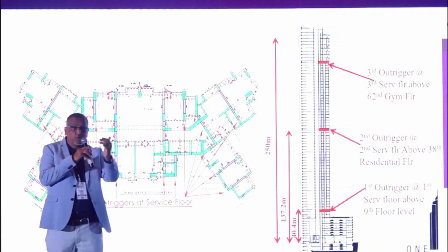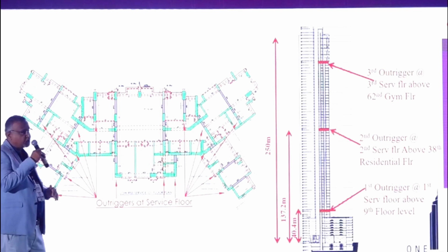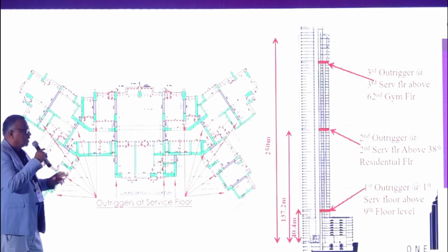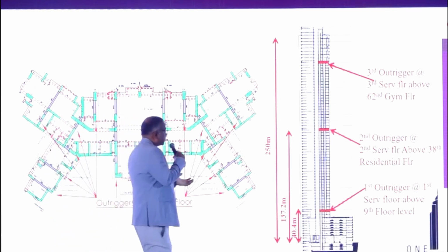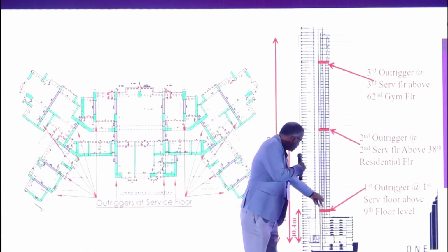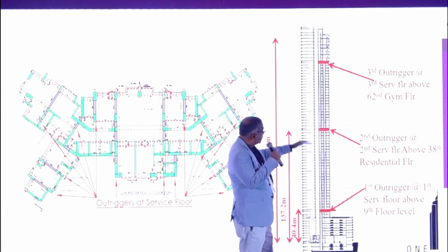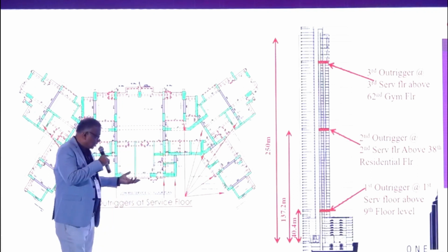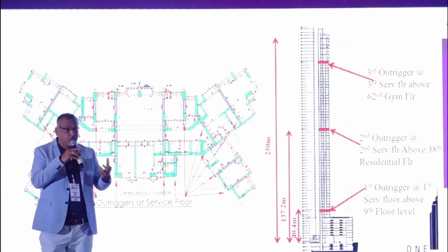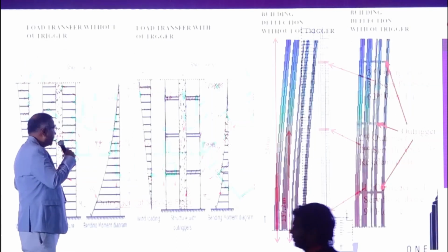We were deficient of the total permissible deformation. The structure's deformation under wind load was not under control. And then we utilized a structural system that is called an Outrigger. So there are 1, 2, and 3 Outriggers provided at these 3 levels. And because of this, I will explain how we reduce the deflection. So in the next slide, I will explain that.